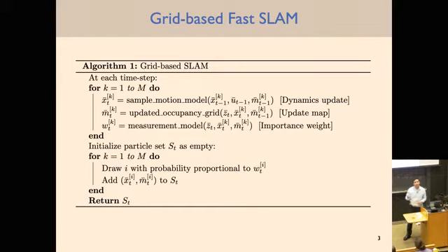All right, here's maybe a relatively simple way. At the end of this process, at time step t, we have capital M particles, and each of them has some likelihood associated with it. That's the WT. So we can just do maximum likelihood estimation. You pick the location in the map that has the maximum likelihood and treat that as the ground truth.